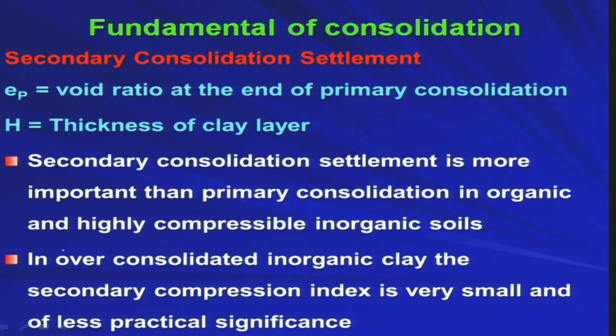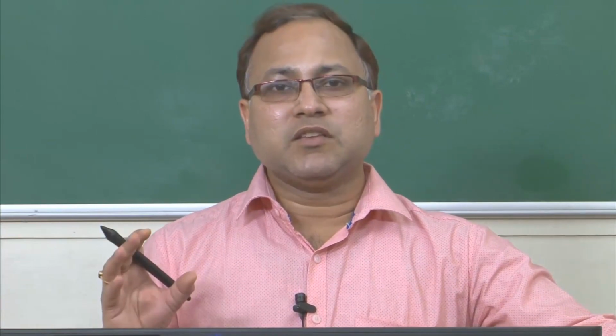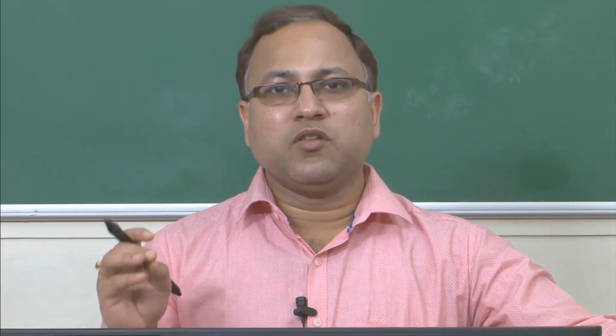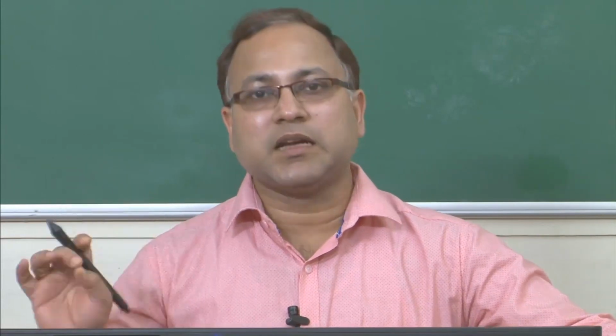So, that is why for most general cases, people only calculate the primary consolidation settlement and based on that they design the whole structure, right. The secondary consolidation will be much lower than the primary consolidation settlement in case of normal soil, like over consolidated soil. In case of that type of soil, primary consolidation has to be given more emphasis than the secondary consolidation. So, that is why people are not that interested in finding out the secondary consolidation settlement, because it depends on time.